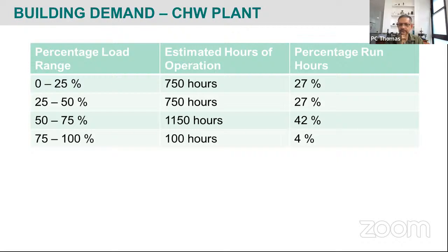If your client is willing, you can have a negotiation with him to say, look, when the temperature outside gets over this value, then we won't be able to maintain strictly 24 degrees centigrade. It may go to 25 or it may go to 25 and a half. Are you okay with that? In that case, we can make your chill water plant much smaller.